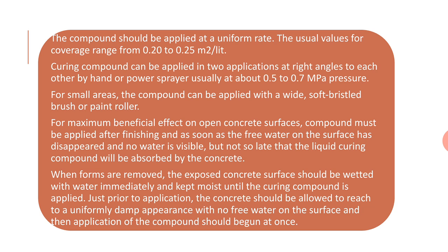Meaning the surface moisture is required to be invisible, but the inherent moisture of the concrete shall not be evaporated. That much delay is not acceptable. Otherwise, the moisture of the curing compound will be absorbed by the concrete. That shall not happen.